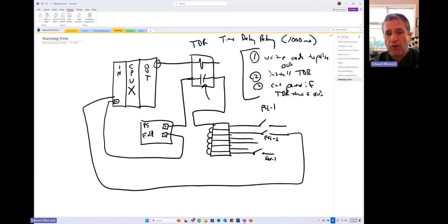So the program can be firing and the output to the field might be frozen in place. And I will get back to that because basically what we're going to do is wire our output back to an input. But that's still to come. So I will answer that question when I talk about how we're going to detect a stuck output and bring ourselves to a safe state.